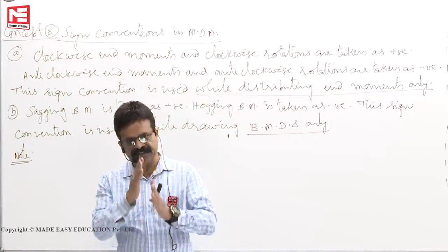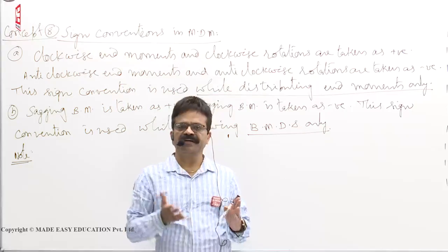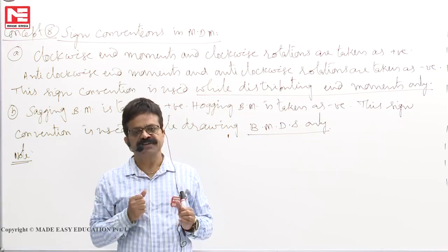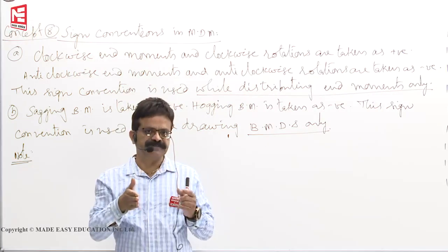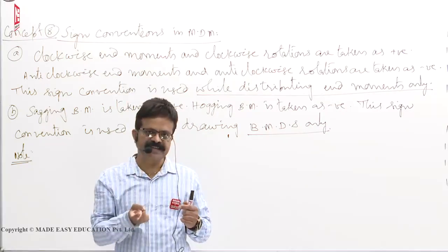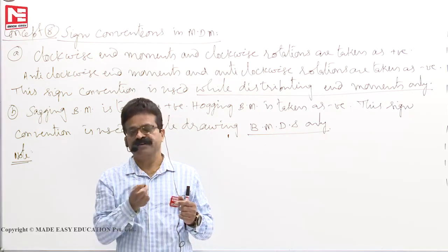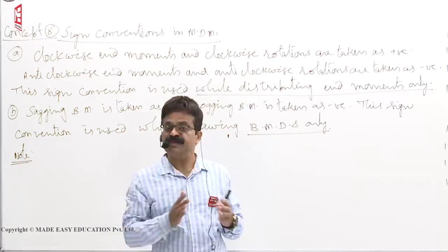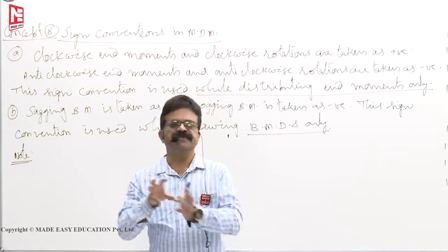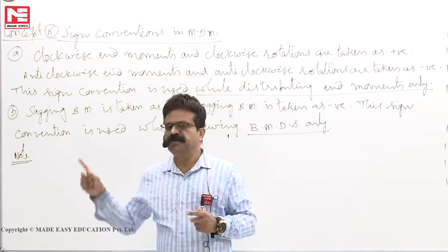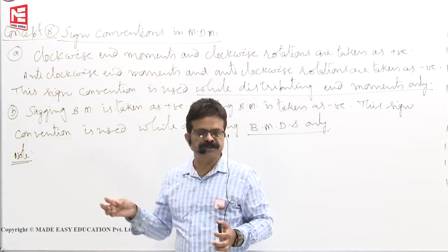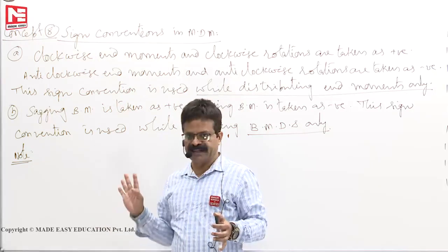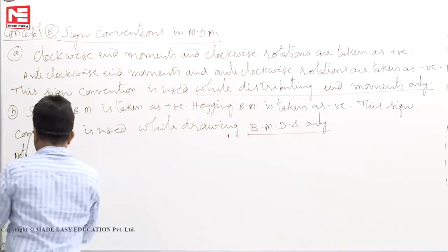Then that shear deflection or shear deformation, where will you consider it? In concrete, when you have a deep beam. In our steel structures, you will consider it when the web is not solid, that means Vierendeel trusses, lacing, and built up columns with lacing and battening. There the shear deformations you cannot neglect. Those special cases we will see in the design of steel structures. But here, when you are analyzing by moment distribution, slope deflection or matrix methods, the shear deflections we neglect.